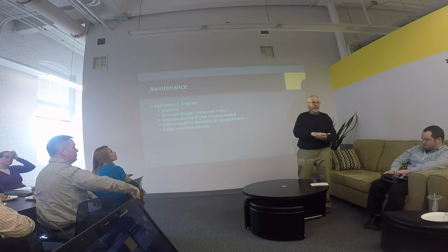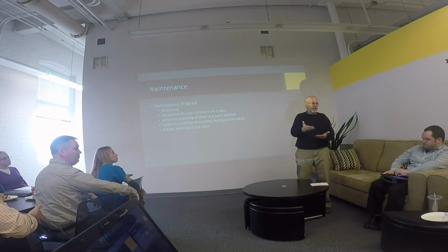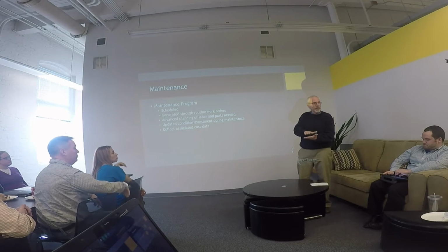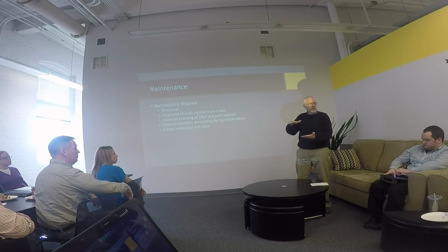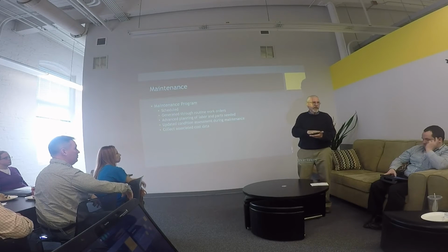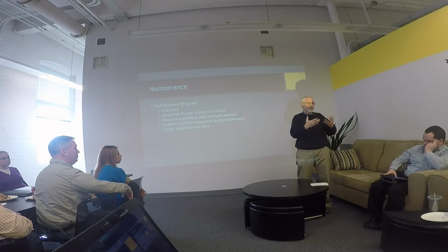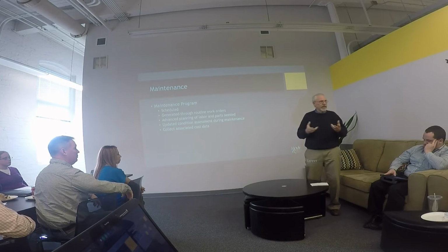Another way of condition assessment is the PACP, where it's cumulative. So 1 is good, but as you add in defects, it goes up to 5, and 5 is failure. So you develop what your standards are going to be. And then you also want to know who is doing that condition assessment.